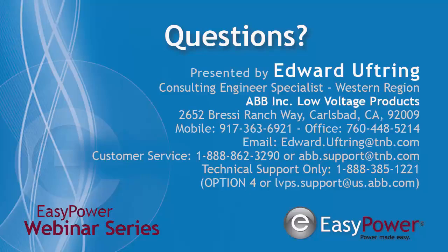The maintenance switch. And then where would you use a maintenance switch on MCC CDs? Maintenance switches usually are recommended on all of them because, again, shutting things on and off, you want to make it as simple as possible. One switch right by the motor so that the person who's actually going to be doing the maintenance on the motor doesn't have to walk all the way back to a cabinet, doesn't have to find the right panel or find the right branch to kill it. He has a switch right by his motor. He can flick it off and know that he's safe down the line.